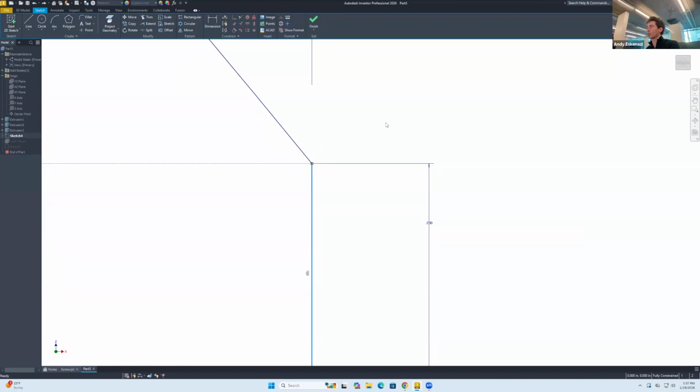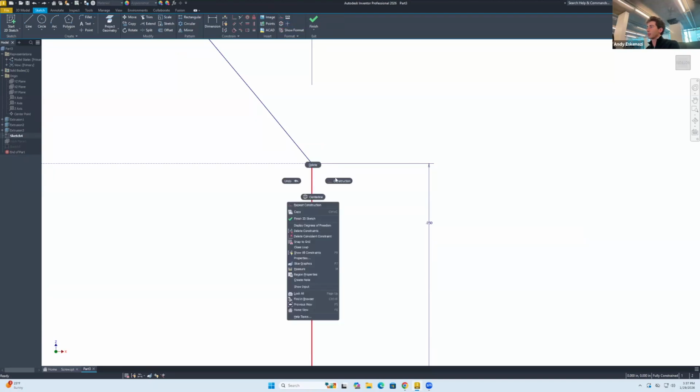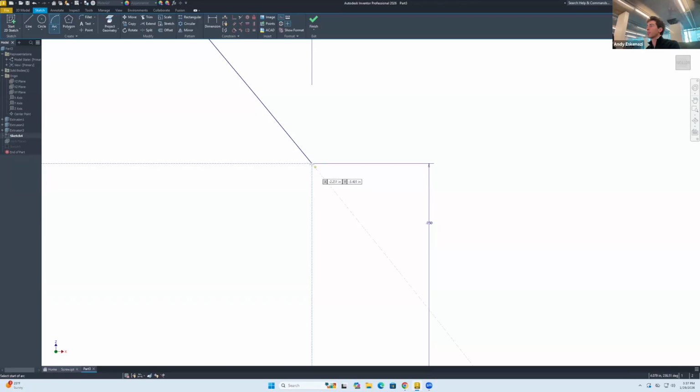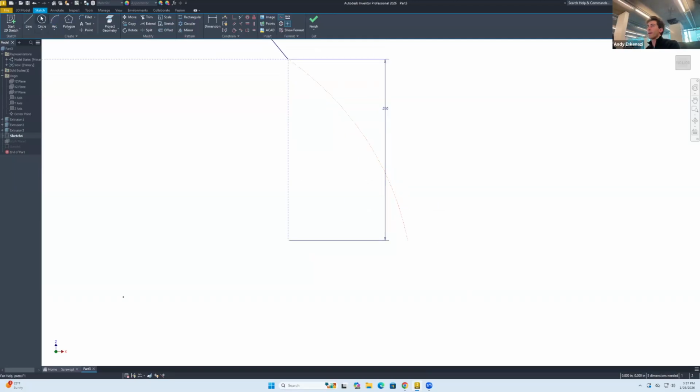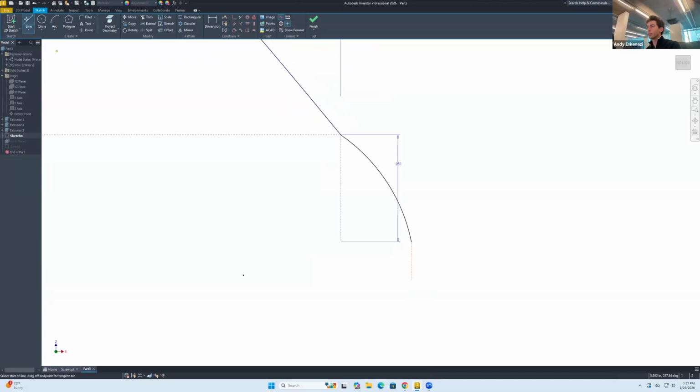this into a construction line and instead of construction, what we can do is just an arc that will go like this. Oh, hello. And what we could define is, I know this is very convoluted, all of this stuff. We're gonna make that like that. Okay. And let me just make another line that will go like this. I will make this line and that line be tangent. Like that. And I will make this line and that line be tangent. Okay, that will work.